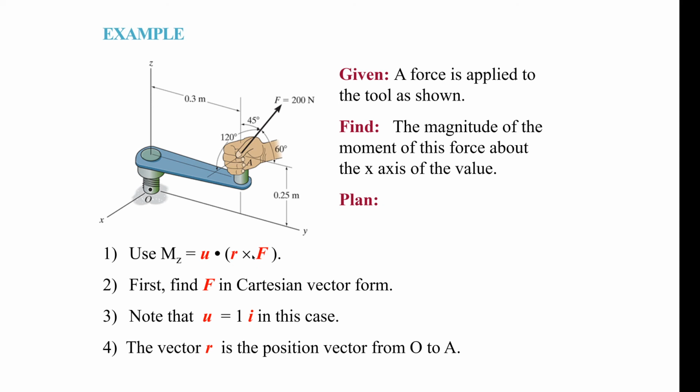First, you have to do the cross product of the vector R from some point along this line with the force. In this case it's given in terms of the origin, or you can find it in terms of the origin. What you recognize is that R represents some point on this axis. Anywhere along this axis, if you do the cross product, it'll give you the same result.